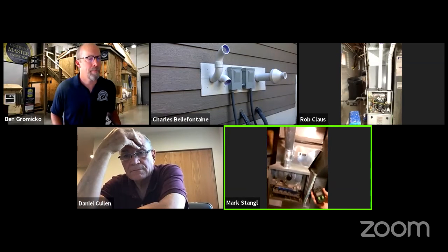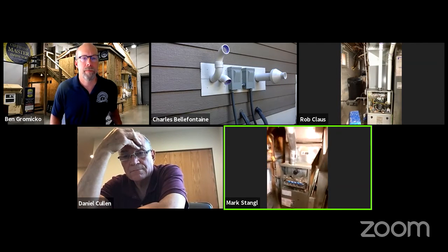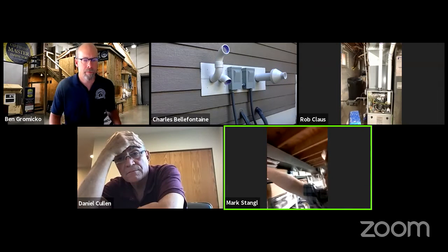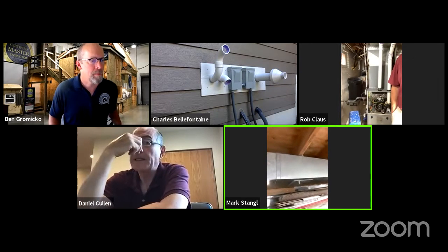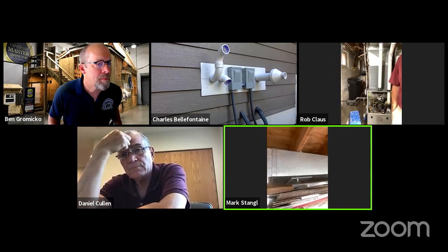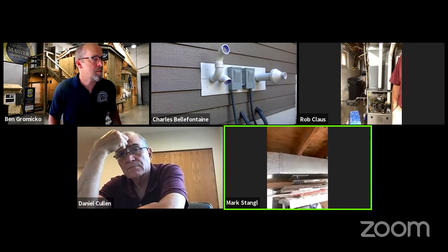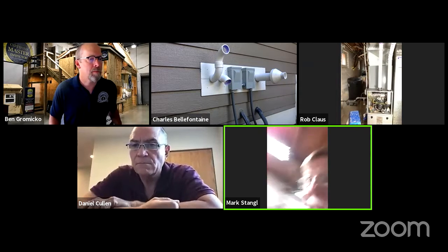It's like a dose meter, but once the burner starts, once the fan comes on and I hear it coming on, I'll go to a heat vent. It only has to run for a few seconds, about 10 seconds actually. Here's one in here, and the hot air is already coming out, and you can see the sensor opening is right there, and there's also a tube you can put on there as well. You let this run for about a minute, and then you're able to determine if there's a carbon monoxide level, and I'm still at 0 now, and I've tested this system many times, so I'm assured that it's burning properly and there's no leaks in a heat exchanger.